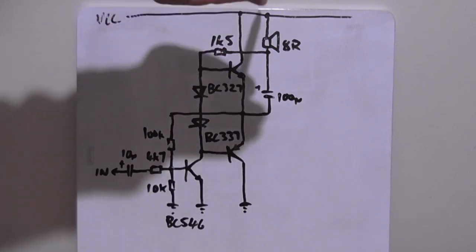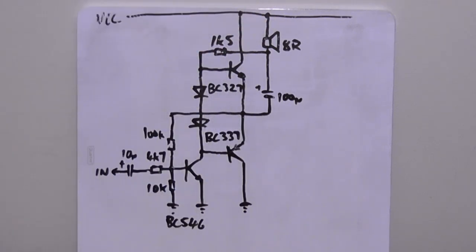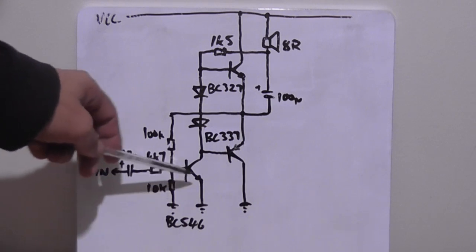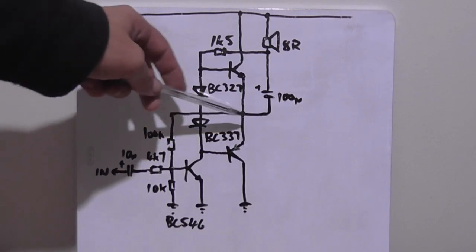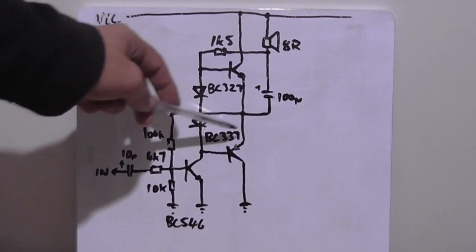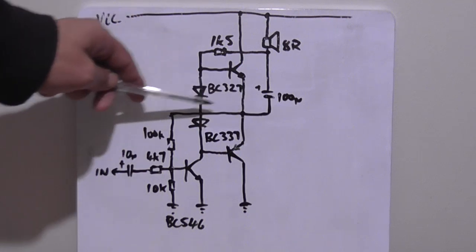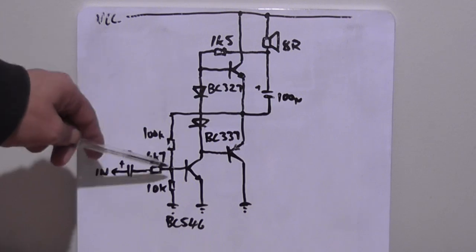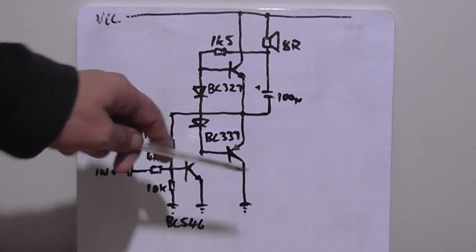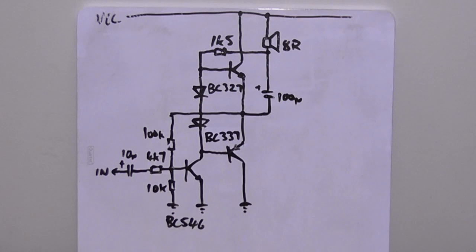So what I want to know is how much DC current is going to be flowing through that voice coil, which will have to be up to testing here. Now this input stage is just a normal BC546 or 547, and it's first being DC biased into class A mode via the output, so it's receiving DC feedback to this transistor and also AC feedback. The AC feedback controls the gain and stability of that transistor so we don't go into distortion. So it's a pretty simple circuit. Shouldn't take that long to breadboard up.